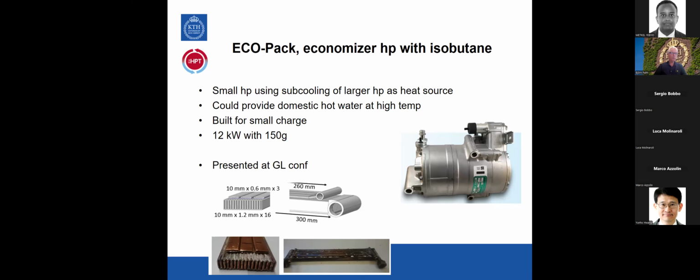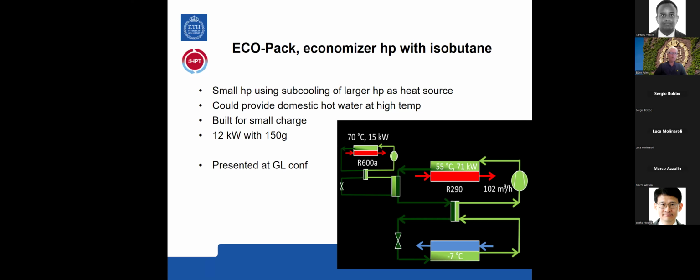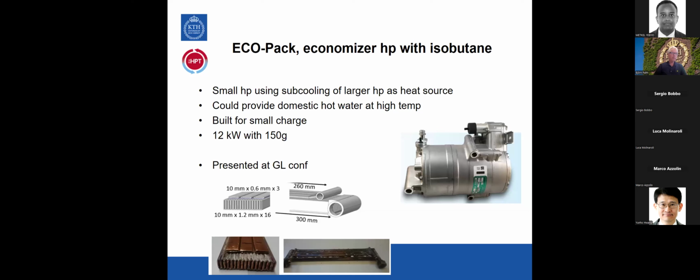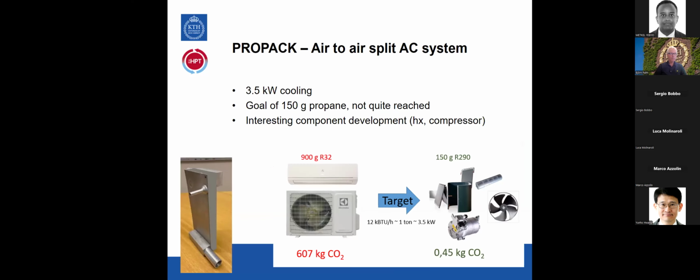We had, as you saw in the scheme, an internal heat exchanger, and of course this is a critical component if you want to decrease charge. So we had to build prototypes as we didn't find anything on the market which was suitable for this, using microchannels, as you can see.